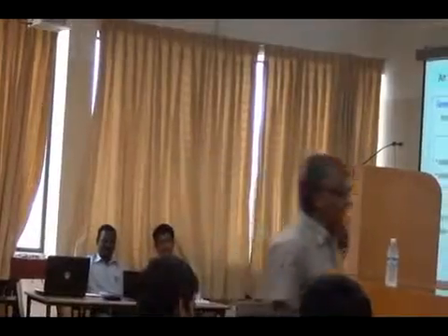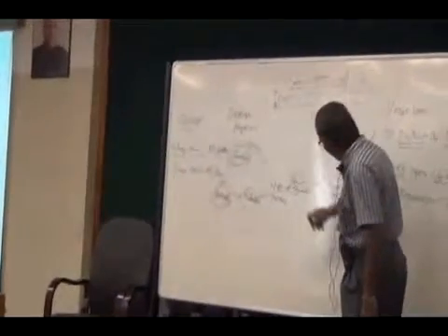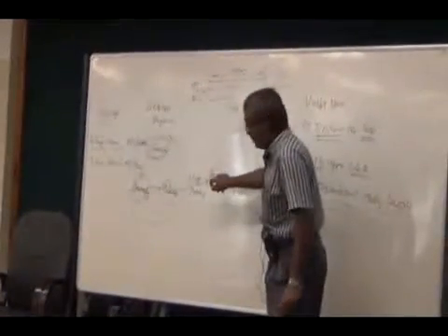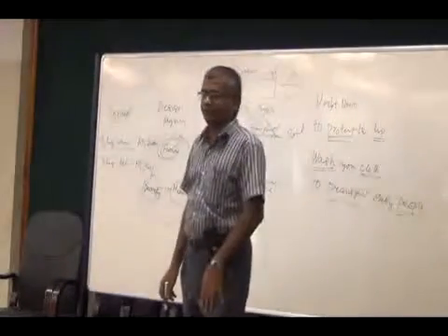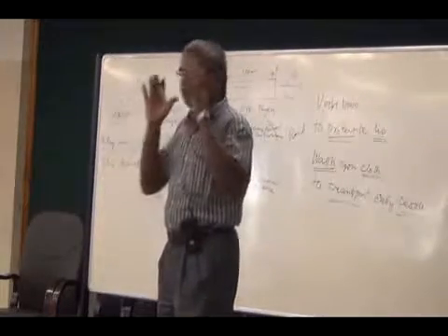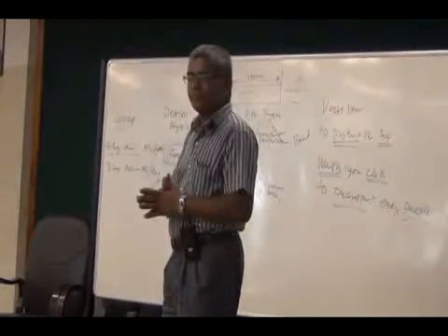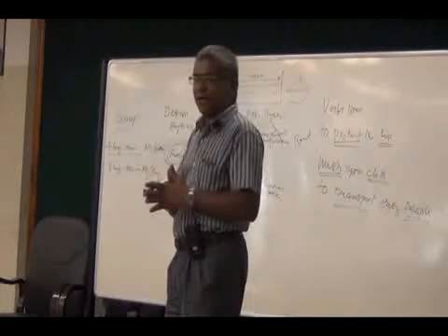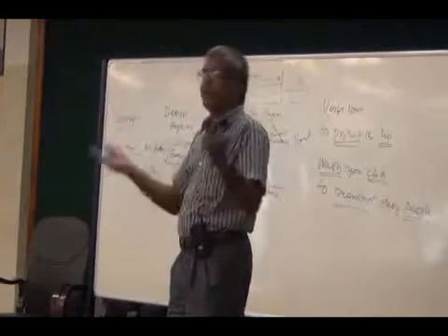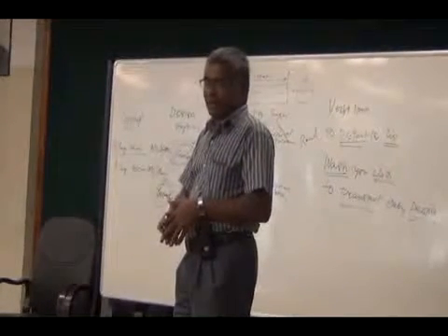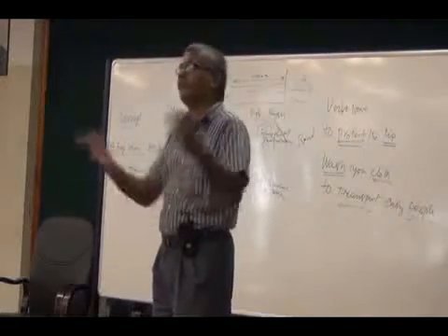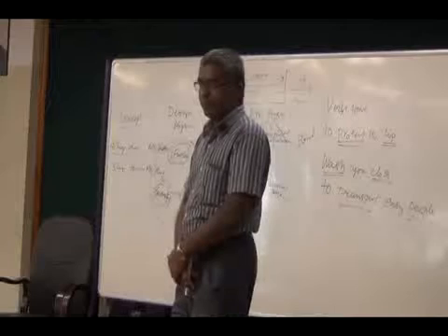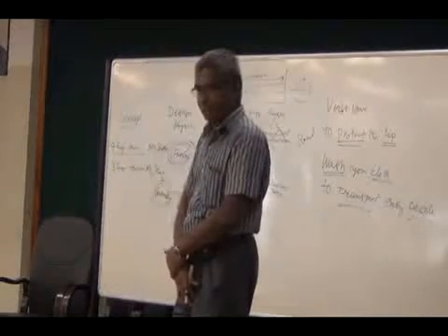So basically, the manufacturing physics gives you certain things, like we need to have a proper grain structure, and material properties are achieved based on the grain structure. The functional requirements or performance is determined by the material property. So design is about choosing the correct functions, and then to achieve that function you need geometry. And for that geometry, only certain materials are suitable, because all materials cannot be manufactured in different shapes. Materials determine the geometry you can achieve.